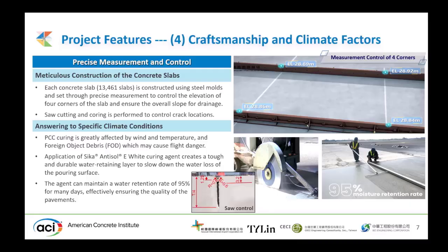Besides the precision, in order to meet the specific high-temperature condition in every area, we apply the curing agent to create a tough and durable water-retaining layer to slow down the water loss. It's an effective way to ensure the quality of the pavement.